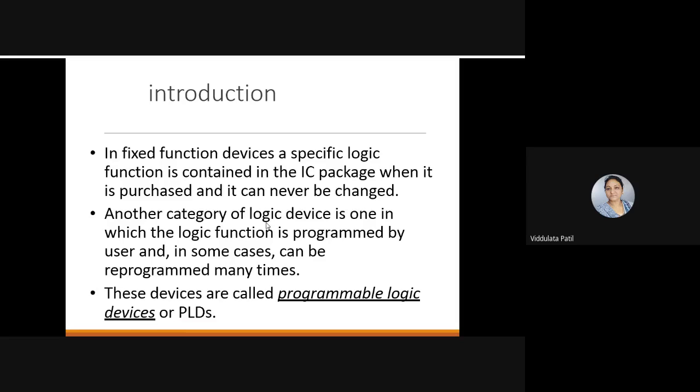Which IC is it? It is a NAND gate. Okay, and 7800, actually the 78 series, is available as a series. So 78 and then there is a certain number, and that number specifies that it is a positive voltage regulator. But these are analog ICs, the 78 series, whereas 7400 is a NAND gate IC. So it is a digital IC or logical circuit.